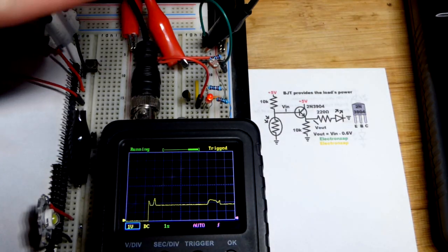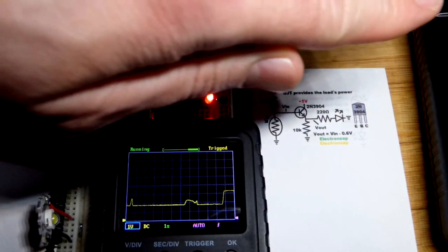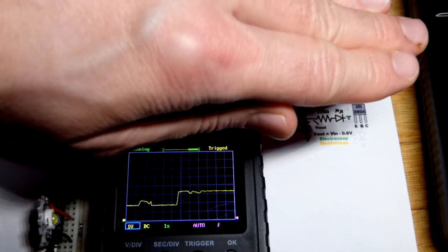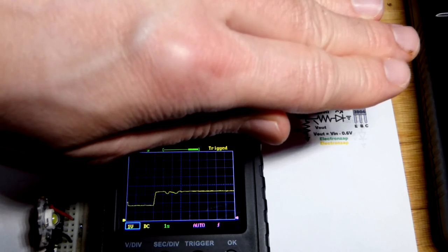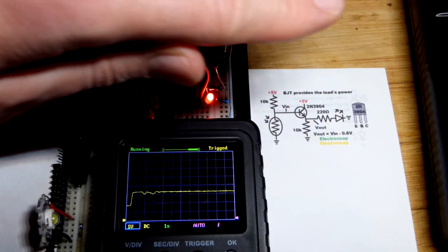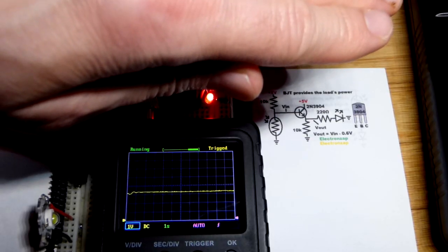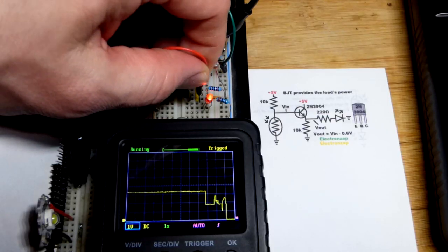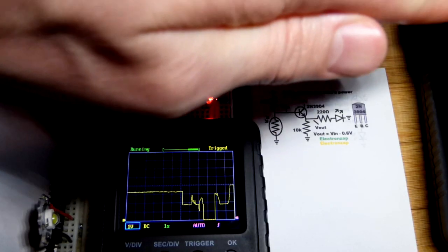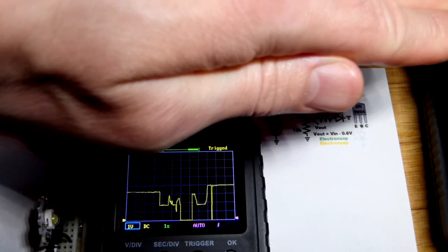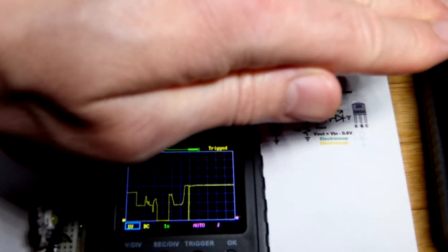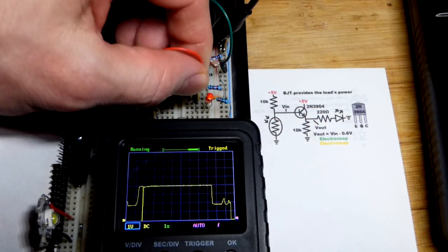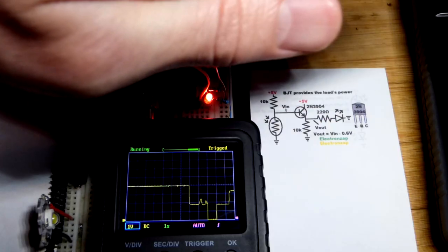Of course, I'd shade it so you can see it better, but I'd also shade the light dependent resistor, so I can't really do that. In any case, there we go. Now you can see we've got a little bit more than 3 volts, and the LED was lit up as we saw. Now we're measuring the voltage across the LED, a little bit more than 3 volts it looks like. Let's go to the base. Hopefully I can do this quick enough before that slides off. Now I'm doing the same thing. I bumped the wire, that's why we lost that voltage. And then you can see it's about half a volt higher. So that's the base when it is darker, with my hand covering it, versus the LED.